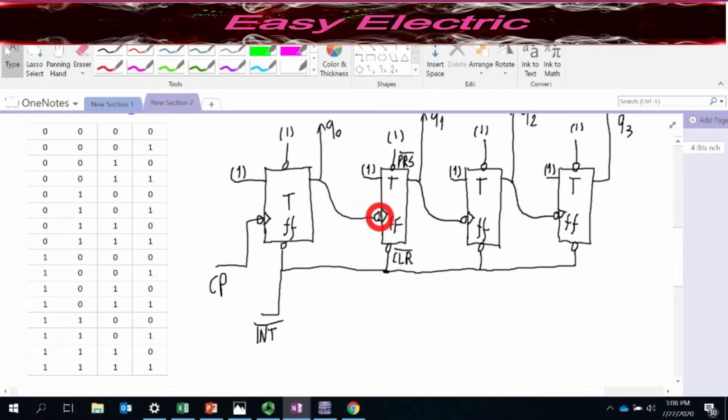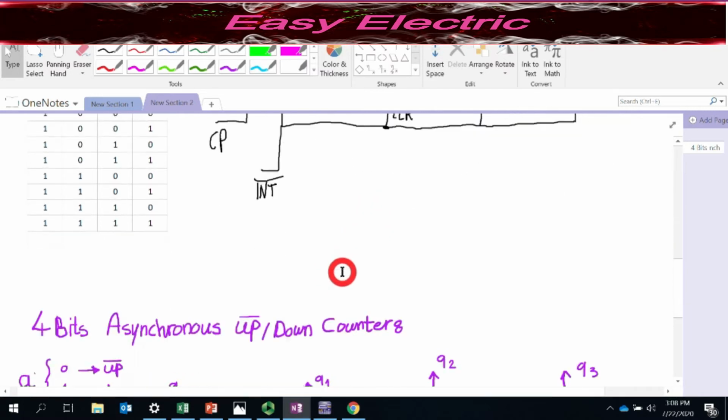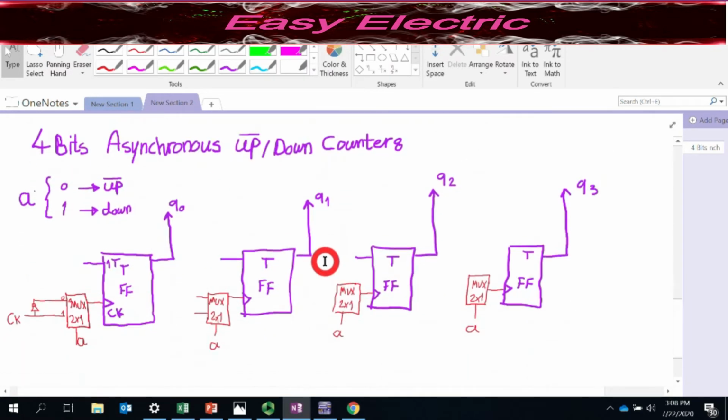That means whatever you connect here is Q0 NOT, because you use just rising edge. You need to have this NOT that you see. For that reason, I'm not connecting Q, I'm connecting Q0 NOT to this pin 0, something like this, okay? So Q0 NOT, right?